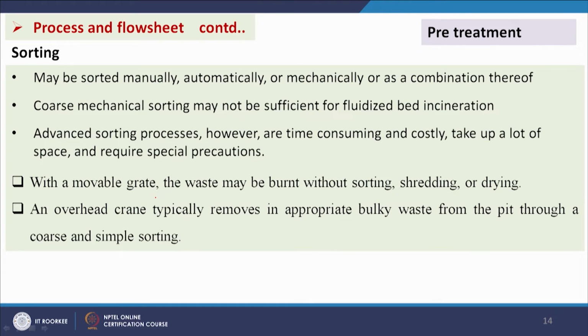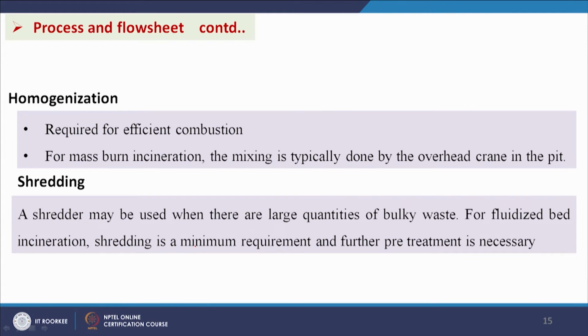With a movable grate, the waste may be burnt without sorting, shredding or drying. So, grate firing is implemented in many cases, and an overhead crane typically removes inappropriate bulky waste from the pit through a coarse and simple sorting. So, that we have shown in the previous slide, in the previous flow sheet.